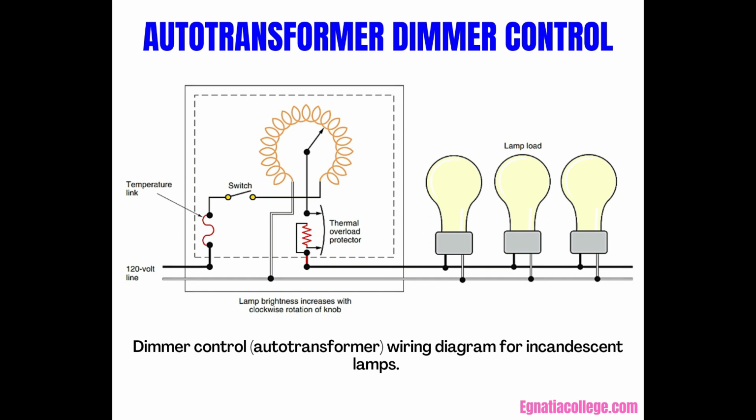In general, overcurrent protection is built into dimmer controls to prevent burnout due to an overload. Instructions are furnished with most dimmer controls to help prevent such burnout. These instructions state that the dimmers are for control of lighting only and are not to be used to control receptacle outlets. Serious overloading of the dimmer could result, since it may not be possible to determine or limit what other loads might be plugged into the receptacle outlets.